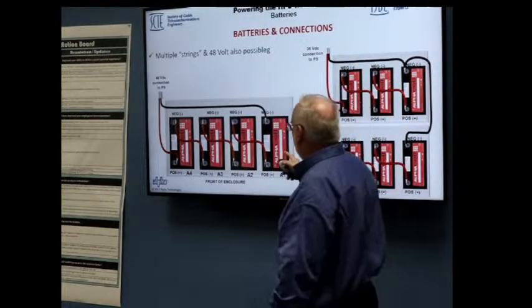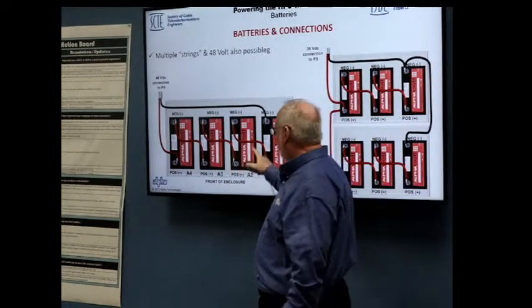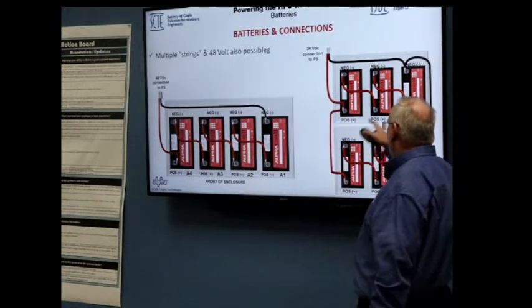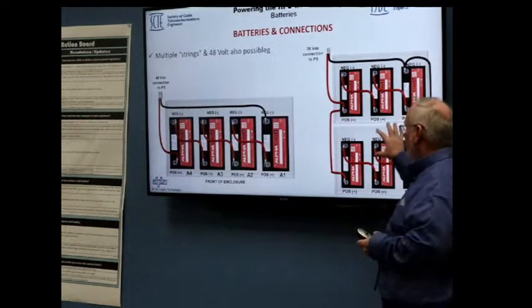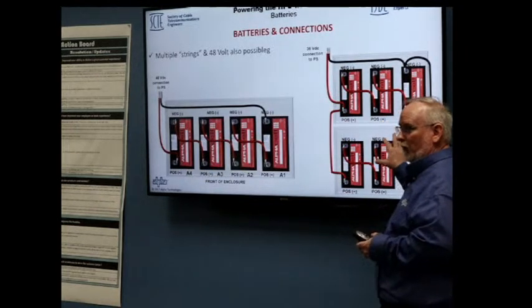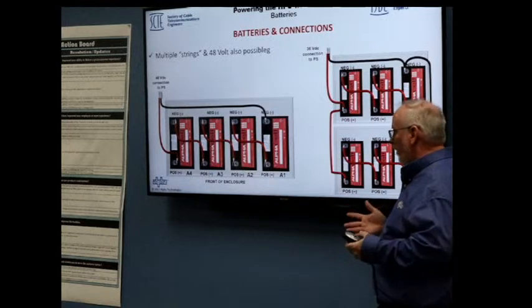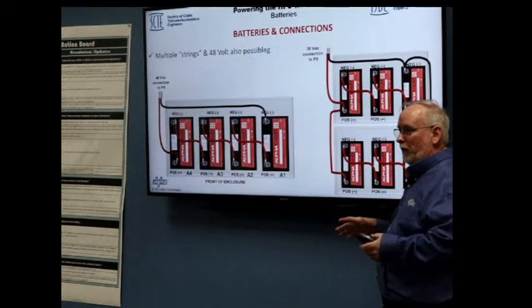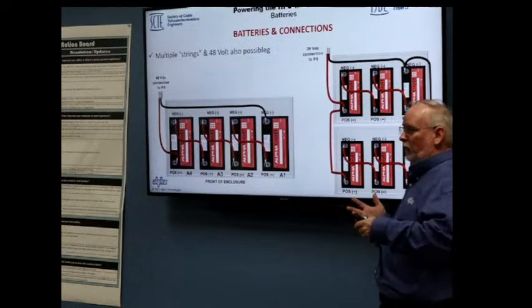So batteries can be connected. This is a 48 volt string. Simple enough, I just add in one more battery. And I can also do a parallel arrangement. For batteries in parallel, check with the battery manufacturer, but the rule of thumb is 3 in parallel max, okay? Some battery manufacturers will do more. We have batteries that we can stack 4.